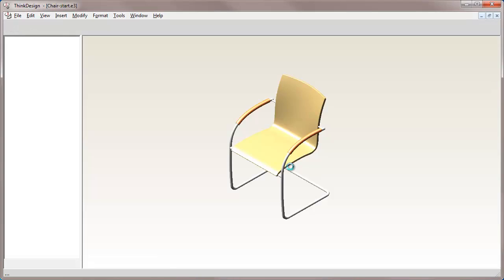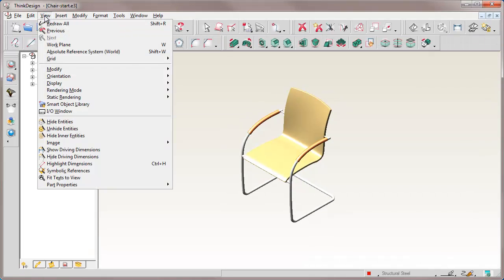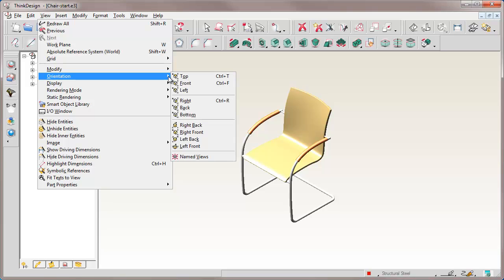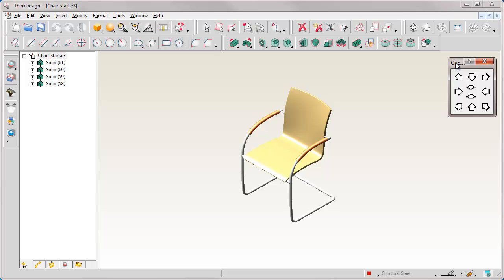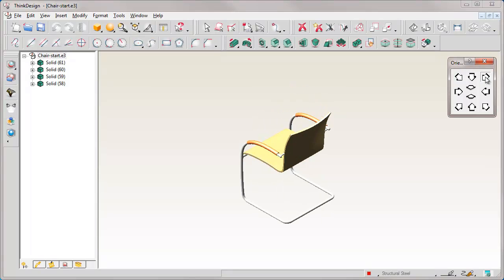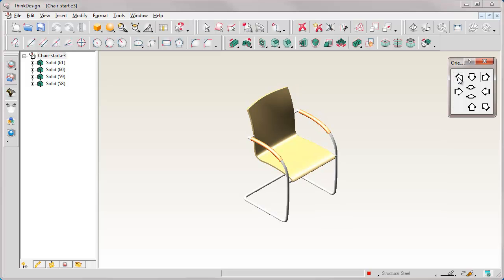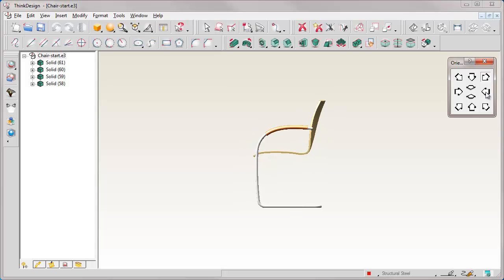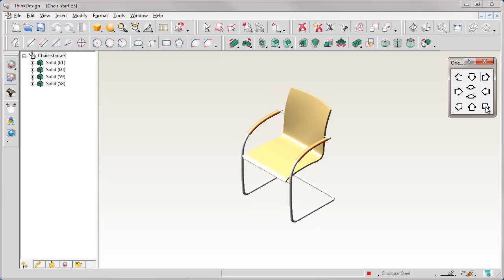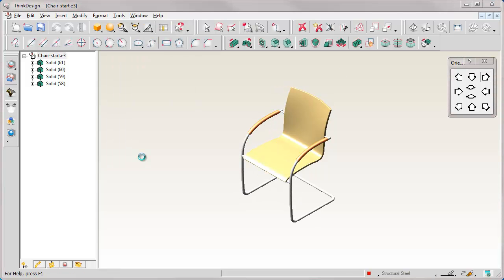Now let's activate the panel to manage the predefined views, and we place it. This rendering mode represents a compromise between photorealistic quality rendering and basic rendering. Rendering is performed with less accuracy in fast mode, but we can interactively rotate the model and see in real time a preview of the effect applied. The number of lights that can be applied is 8.